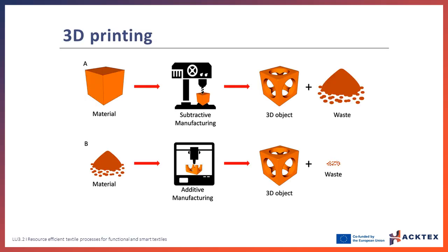The world of 3D printing holds a wide range of technologies. At the highest level, there are three major categories for production of a 3D part, including forming, subtractive or additive manufacturing. In forming, the material will be reshaped. In subtractive methods, as you can see in the figure, unwanted material will be removed from the 3D object with different methods like cutting or etching. In additive manufacturing, the 3D object will be formed by a layer-by-layer building process.